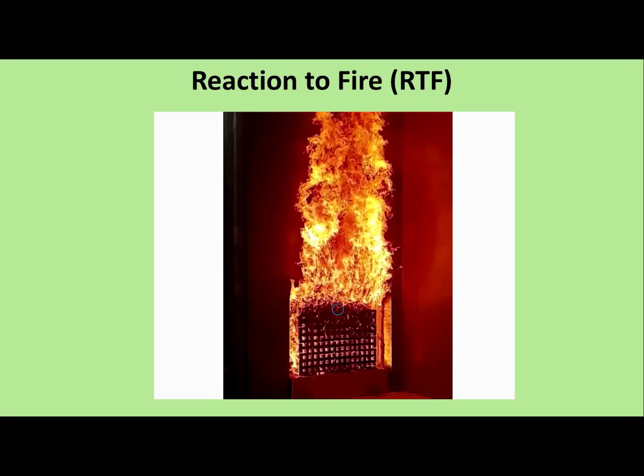This is the first of probably 2 or 3 videos that relate to the fire tests that pertain to Approved Document B. And the first one we're going to go through is the reaction to fire. Now, reaction to fire effectively has replaced the surface spread of flame that we have had for years that has been tested to BS 476 Part 7, Classes 1 to 4, and BS 476 Part 6, which is Class O.